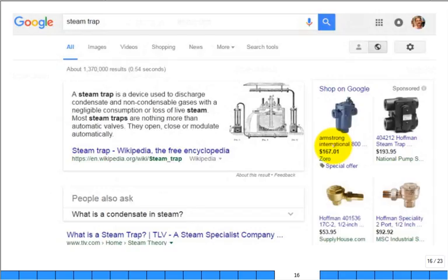There's a lot of different types of steam traps, but the idea is to discharge the condensate and any non-condensables, because air gets in there. In our power plant analysis, it's pure water, no air in there. But when air gets in there, it doesn't change phase or condense, and it ends up accumulating in certain spots. Where it accumulates, you've got to get it out of there. So they'll have blowdown processes, or they'll have this steam trap, which will have two areas to let the liquid through, and also a mechanism to get the air out.